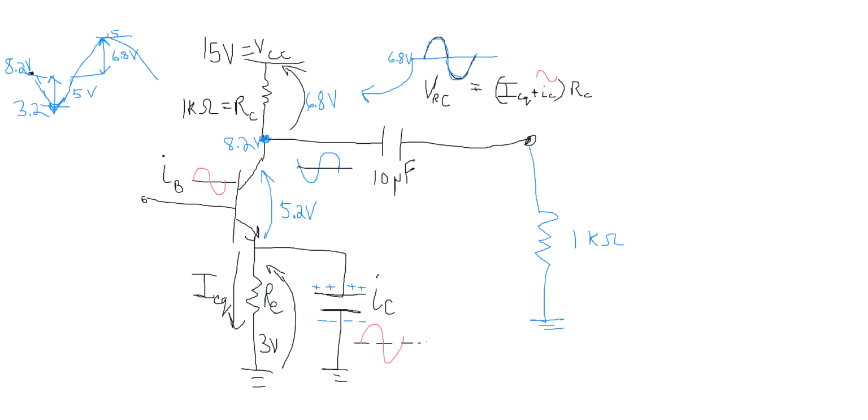So what's happened really is that IB is pushing 5 milliamps more of current in. I don't want you to associate it with the voltages so much as IB is demanding 5 more milliamps. Okay, so before without a load, that 5 milliamps translated into 5 volts more at RC, that brought us to the floor, so we couldn't really do any more. Now I have a load resistor. And that load resistor is going to respond to AC changes because the capacitor will allow that current to flow.